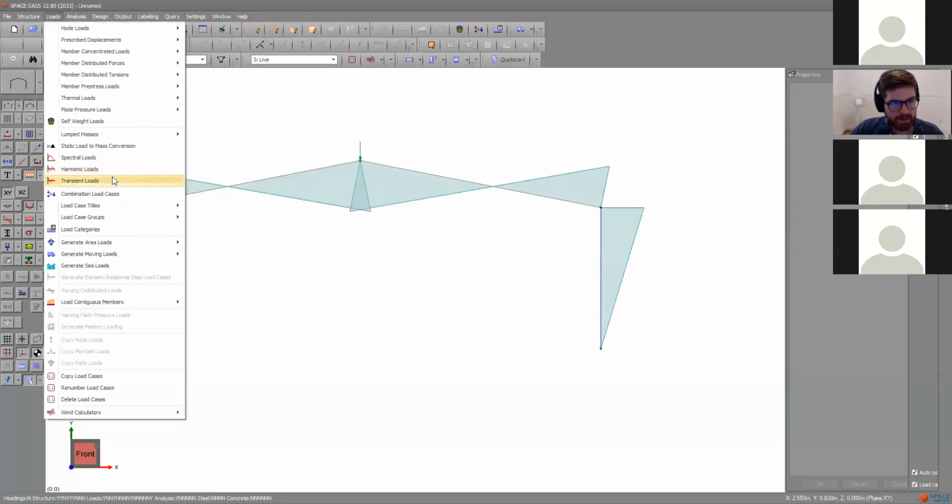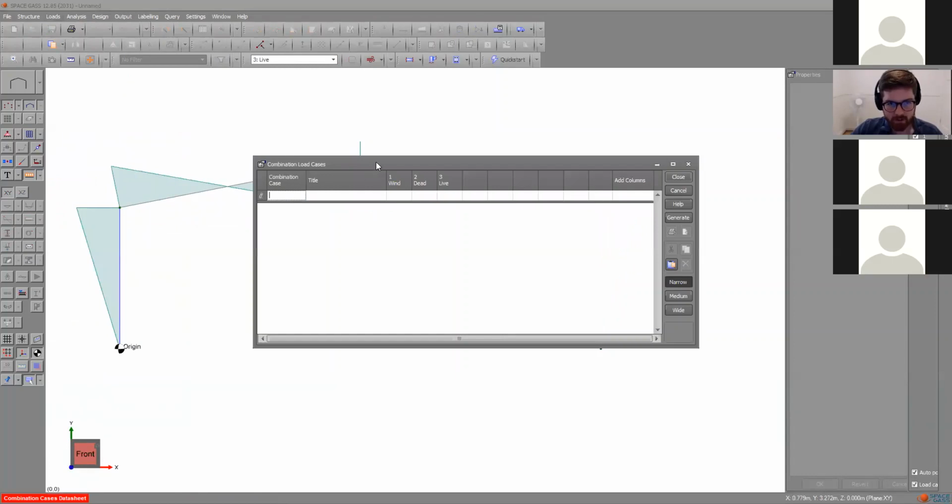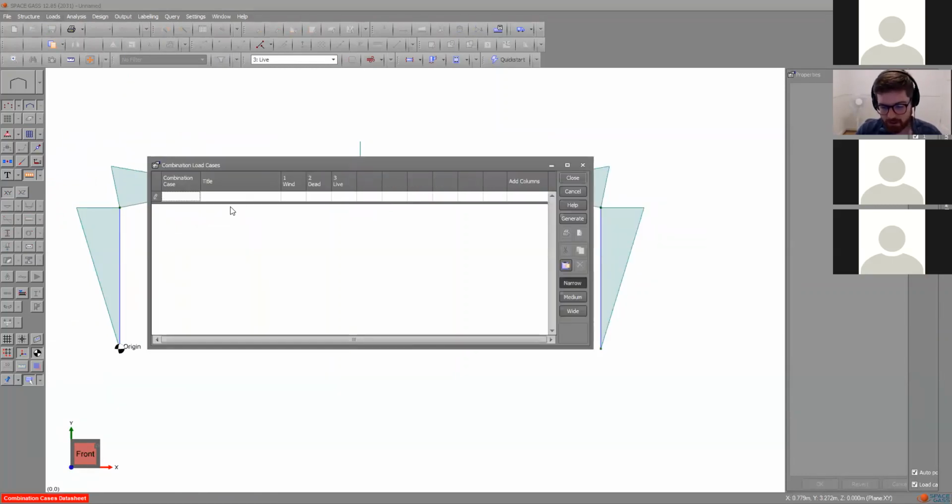A useful thing about specifying those loads separately is because you can then build combination load cases. So particularly for those of you who are going into Civil 3350 or are currently taking civil design, all of your actual design work will use a combination load case. It's not going to use an individual load like you might be seeing in some of your second and third year mechanics courses.